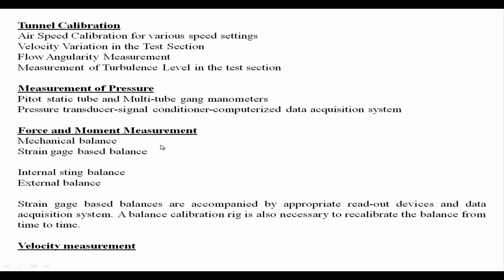Force moment measurements, yes, again a whole lot of options: mechanical balances, strain gauge based balances. Again, how are you going to deploy them? Are you going to deploy them in the form of internal sting balances or external balances, or there could be still better methods of doing things. So, you can do a bit of reading to find out what more is going on.